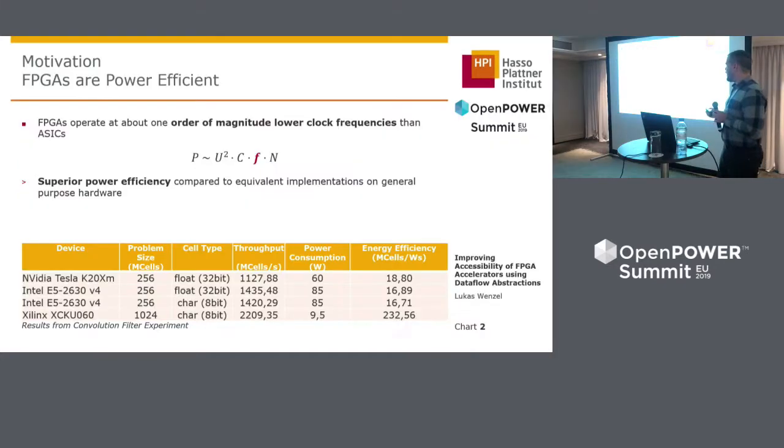So I don't think that I need to introduce the benefits of using FPGA accelerators to this group, but perhaps to highlight one particular advantage that is important to us, at least, is energy efficiency. As FPGAs are able to operate at lower clock frequencies, which are perhaps sufficient, at least for a very large variety of application scenarios, they usually do need only a fraction of the power an equivalent CPU or GPU would use.